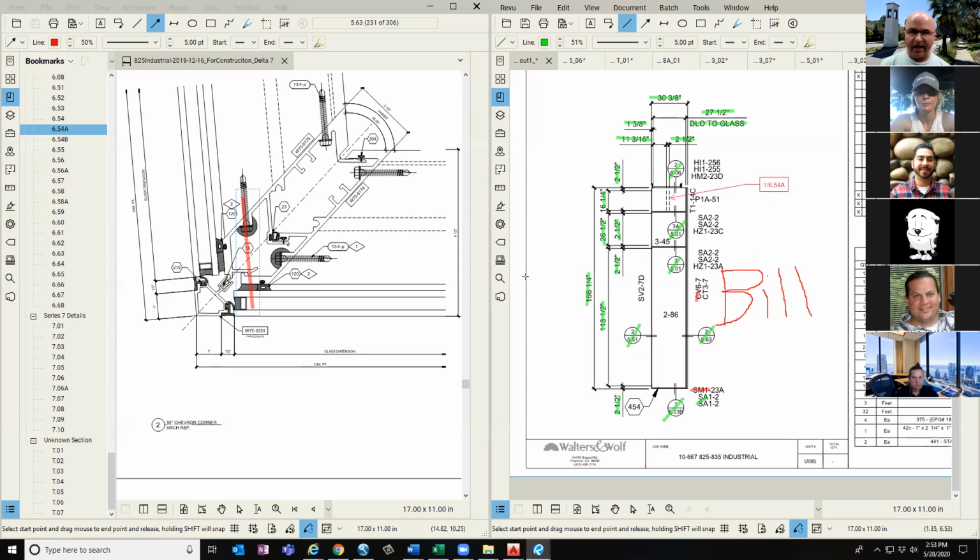But in addition to that, as I'm going through my shop drawings, I'm thinking about how this unit is going to be installed. Will it fit into that opening? Does that deck edge that's occurring up at that parapet near the roof have some impact in being able to get this unit into that position? Will it fit there? Do I have the right miters? So all of these things are going to come into question as I'm making these checking decisions as I go.